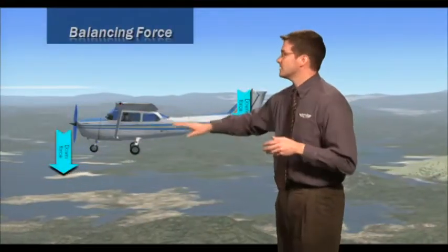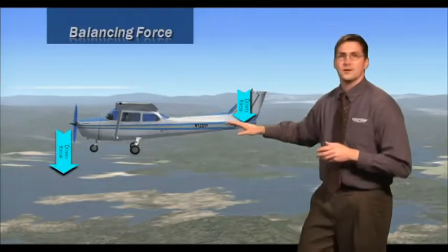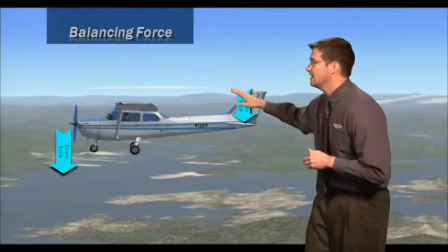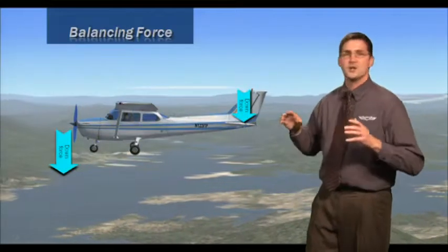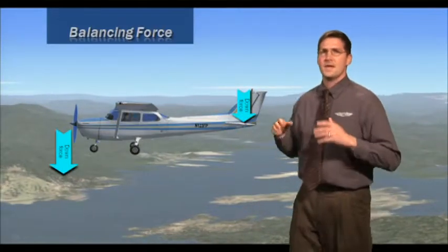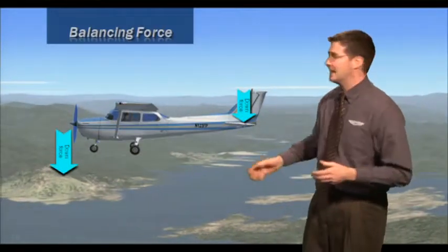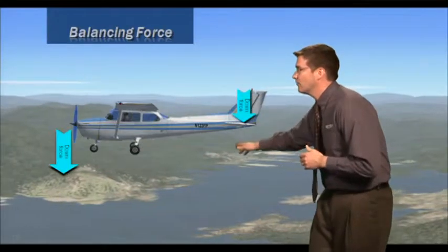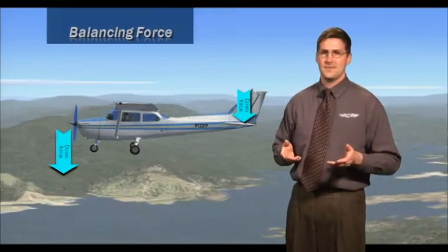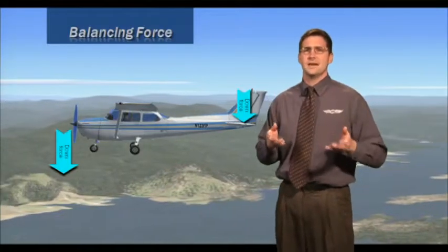These balancing forces are generated by the propeller. As the air moves along the fuselage over the wing, it strikes the tail in such a manner that it impacts the top portion of the tail. That is negative lift, and it is also called a tail down force, and it counteracts that natural pitch down tendency. Now assume you're flying in straight and level attitude.